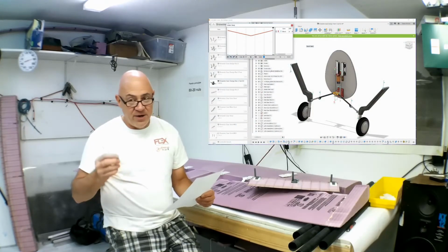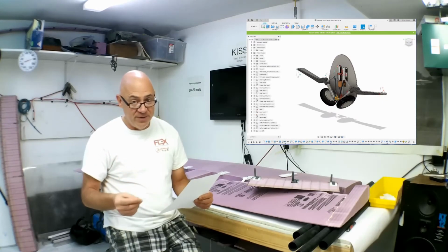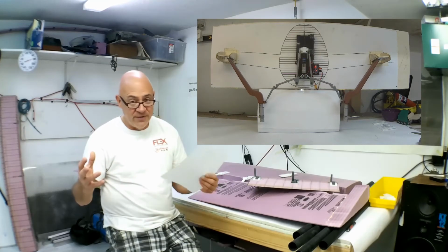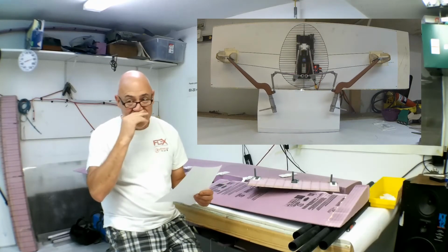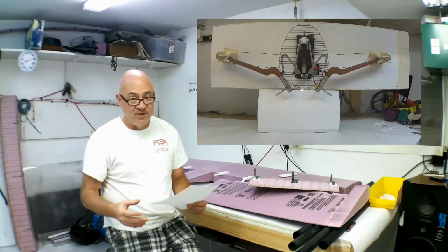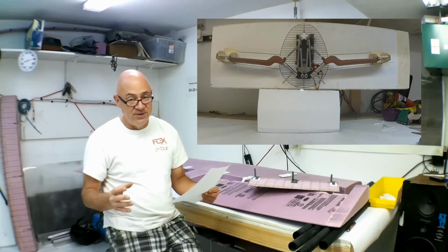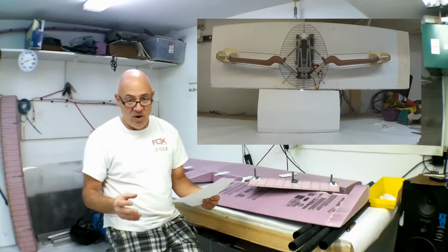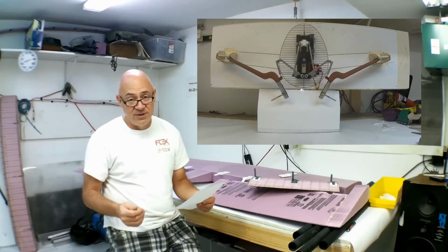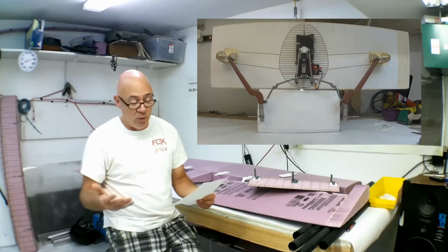But don't be afraid of using steel where steel is needed. Don't be afraid of using aluminum where aluminum is needed. Most of the time, the heaviest components on an airplane are the motor and the landing gear. Literally on the B-36, my landing gear weighed 21 pounds. That's one of the reasons I went to carbon fiber shafts and some other things, because it was just stupidly overbuilt, with stainless steel in places it didn't belong. It was a mess. And I'll never buy commercially made landing gear again. I'll make them myself because I know they'll work and I can control weight.